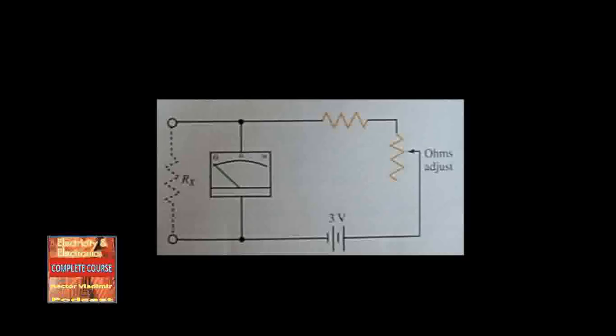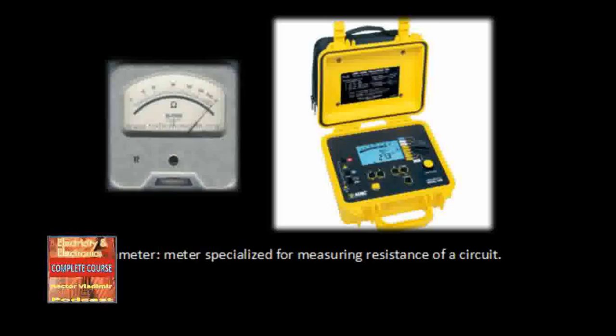Part of this resistance is made up of a variable resistor to allow the total resistance to vary. Because temperature changes or weak batteries can affect the total resistance of the circuit, the ohm meter must be calibrated. Adjust for zero resistance in order to ensure the most accurate reading possible. The knob used for adjusting the pointing needle position to zero is usually marked zero adjust, or with an omega symbol near it.